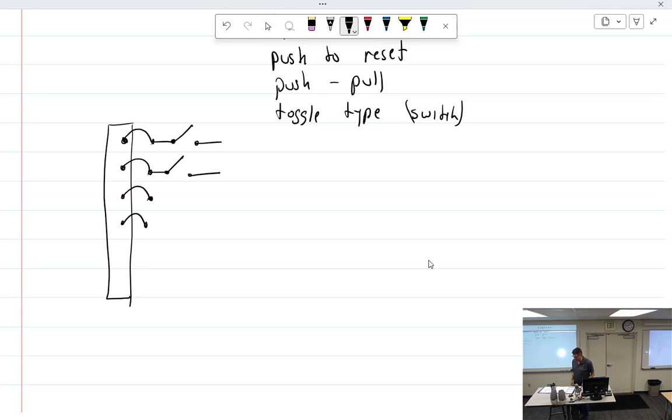I've done that 100 times. Okay, I'm not going to write this down, but in circuit breakers, there are 3 different types. There's the magnetic type. When excessive current flows in the circuit, it creates an electromagnetic force strong enough to move a small armature which trips the breaker. If we have a circuit breaker that's 5 amps, when it gets to, let's say, 5.5 amps flowing through a coil, it will create a magnetic force strong enough to pop the breaker. That's how it's designed. We have the thermal overload.